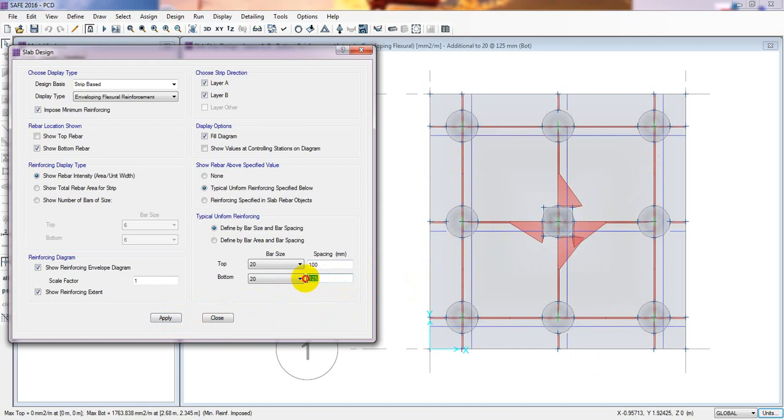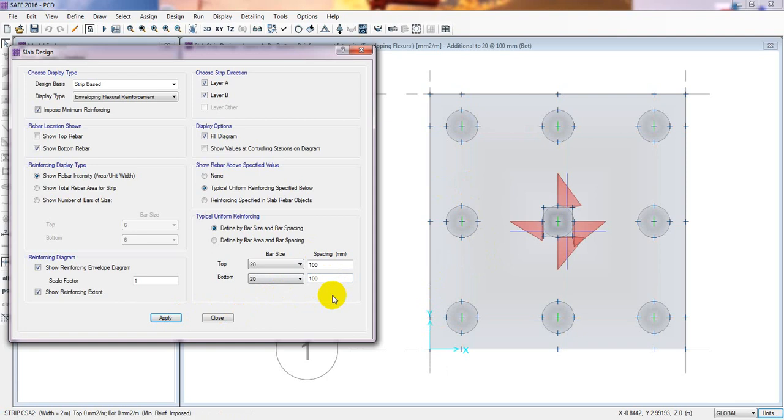Here also okay. So if we go for 100 with 20 mm bar, now see that with 100 and 20 mm bar, every point has covered the reinforcement requirement. We just have to provide some extra reinforcement around that column. So around that column, what will be the reinforcement spacing? First of all we'll provide reinforcement at bottom with a spacing of 100 millimeter with bar of 20 millimeter, and here we will provide some extra reinforcement around that column.